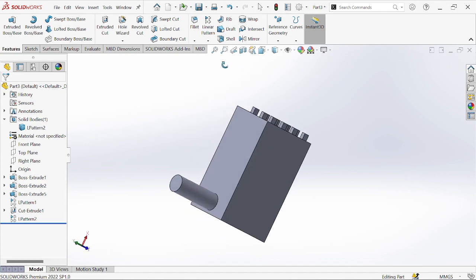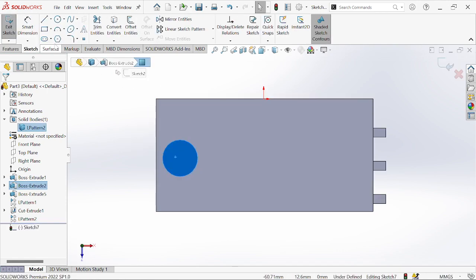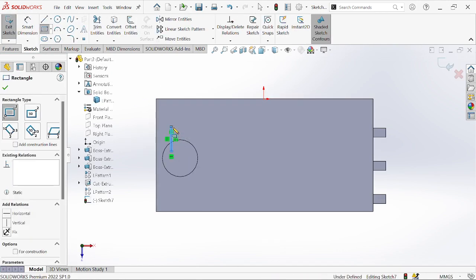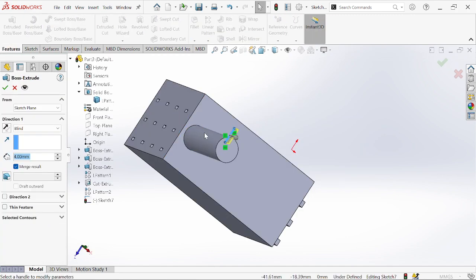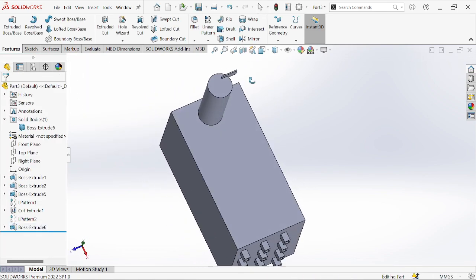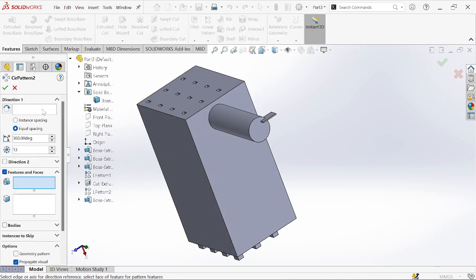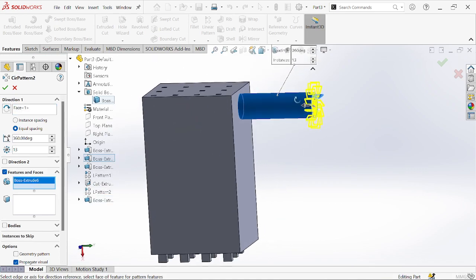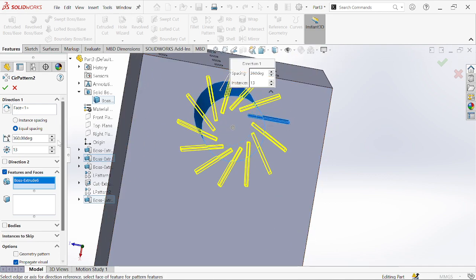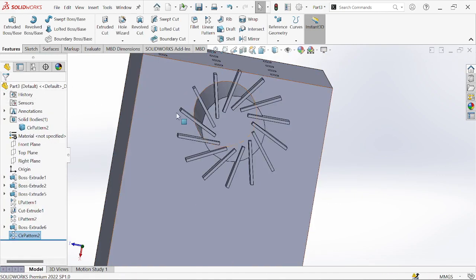Let's see circular pattern where you need a circular face. So like the circular face, and let me create geometry on it. So extrude, first make it 3D. Then click the drop down, select circular pattern. Direction, it will be the circular face. Feature, it will be that both extrude. Can modify the number, the degrees. Yes, you can also skip just like in 2D circular pattern.